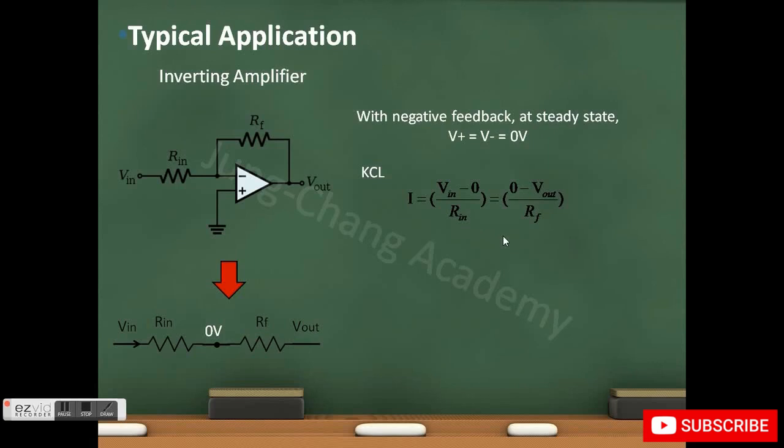Now if we rearrange and simplify this, we know that V out equals minus RF divided by R in times V in. Again, if we put a kilo ohm resistor in RF and R in, we know that V out equals minus V in. So if we have an input like this, the output will just look like this. And this is why this amplifier is called an inverting amplifier.